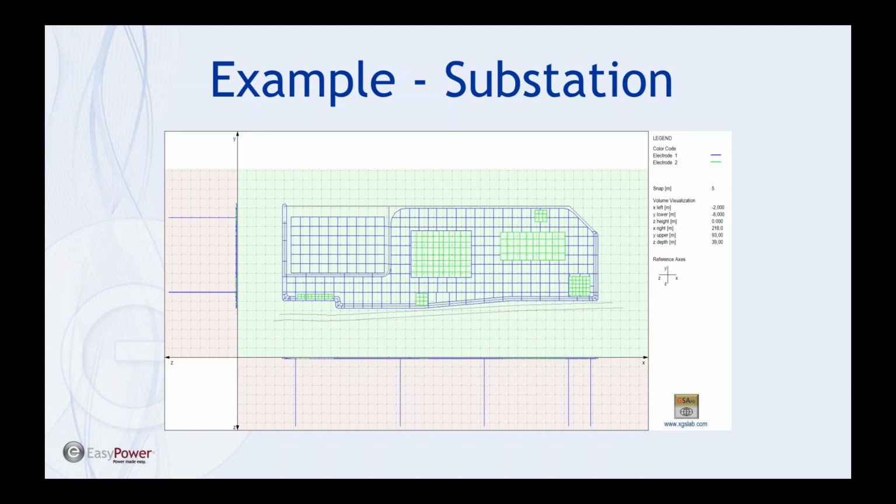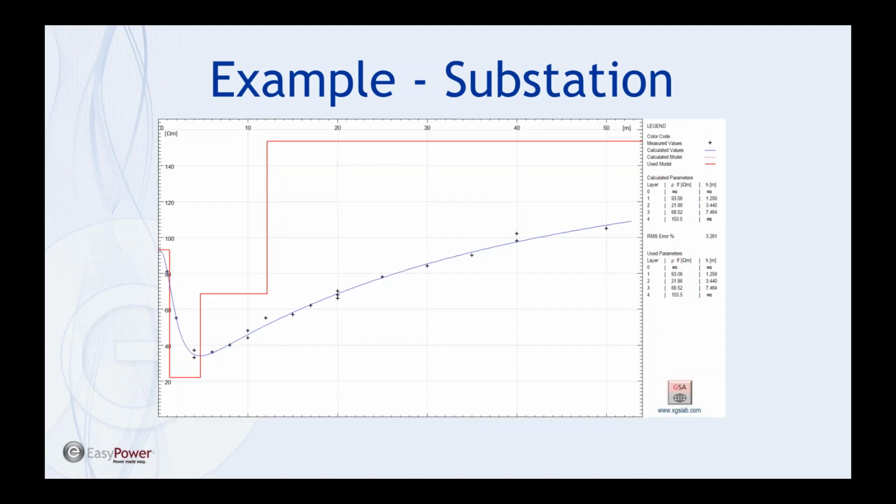And the green are the foundations. You can see that the foundations in this case are bonded to the grid in certain locations. The green in the foundations represents the actual rebar inside the foundation. The foundations aren't generally used as a main grounding conductor, but in a robust grid like this, they can be connected to the grid. This is an example of what you might upload from a DXF file into a grounding program.